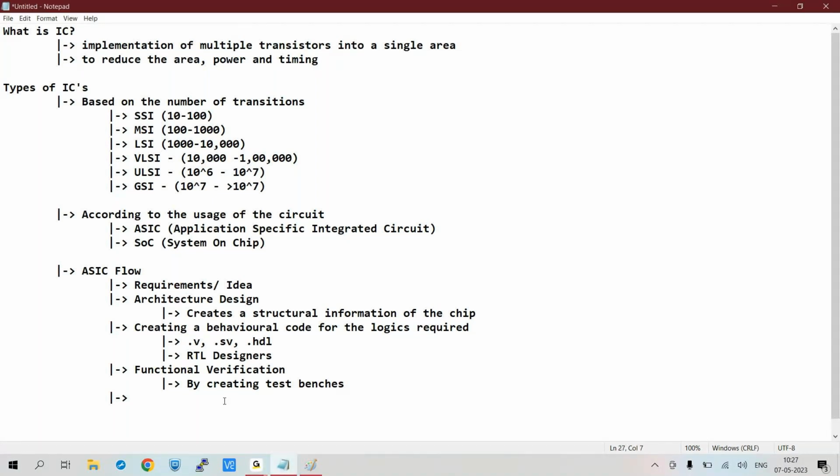That's why. Okay. So now after this functional verification, we can say a single stage called the RTL sign-off stage, where we have multiple tasks running in parallel. We can say linting, CDC.